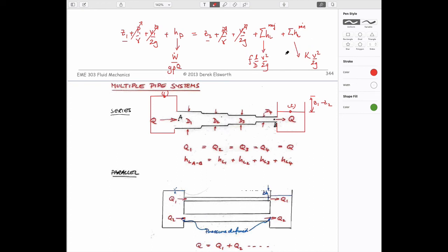In this particular case, if you plotted the head loss between upstream and downstream, it is going to change from one magnitude to the other, and that magnitude is actually going to be this height, z1 minus z2. All that has to be figured out is exactly how that head loss will change between upstream and downstream points. We know that the requirement from continuity is that the flow rates are the same. Continuity is just another way of writing mass conservation.